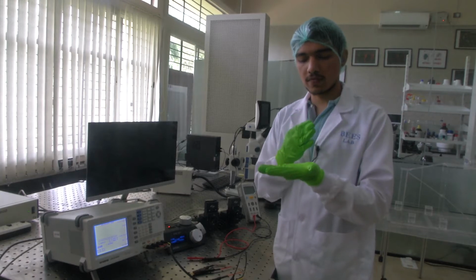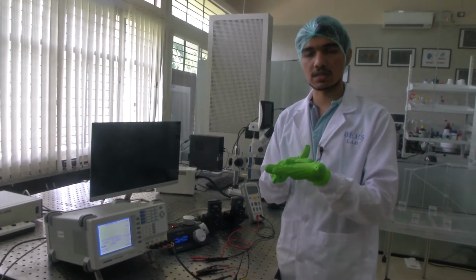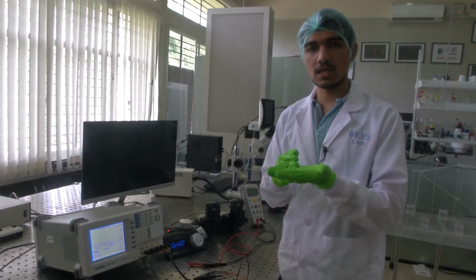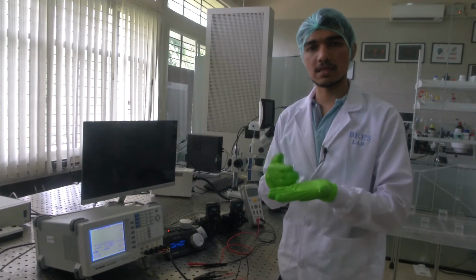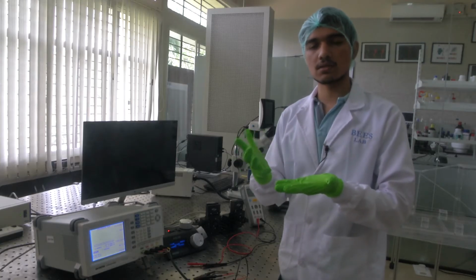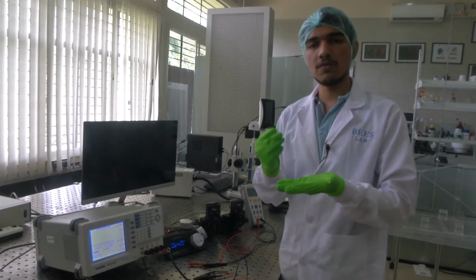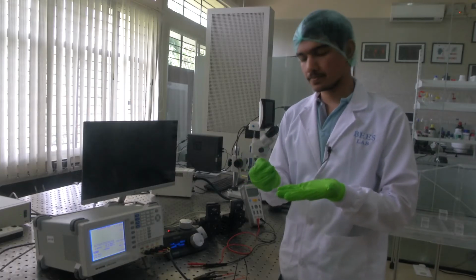Then we will flow a small amount of current through it or apply a potential difference across it, and based on the V by I value, we will measure the absolute impedance, correct. So, to get the impedance with phase, we will do a phase sensitive V by I ratio.